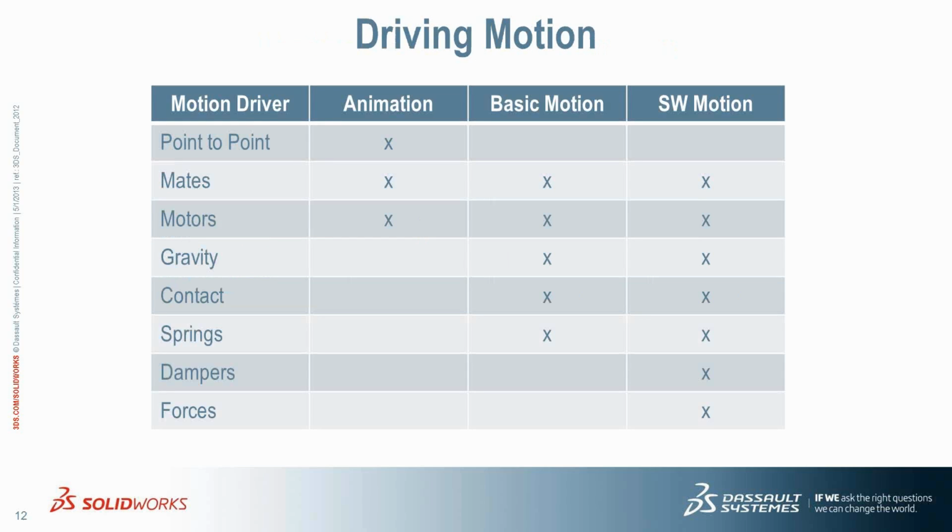We're going to talk about this concept of driving motion today as well. What drives that motion is just as important to help you decide which of the study types you're going to utilize. If you're dragging components point to point, or you're driving using mates or motors, that's where the animation study type is going to come into play.